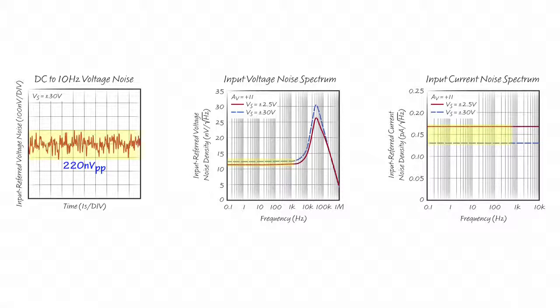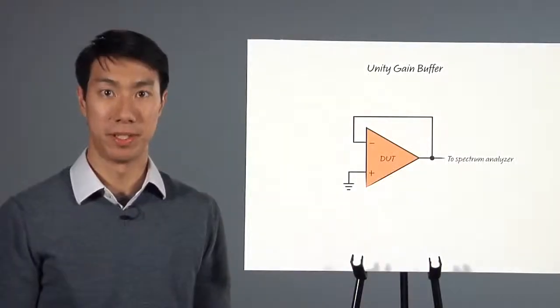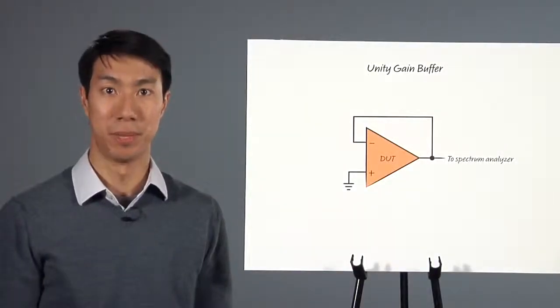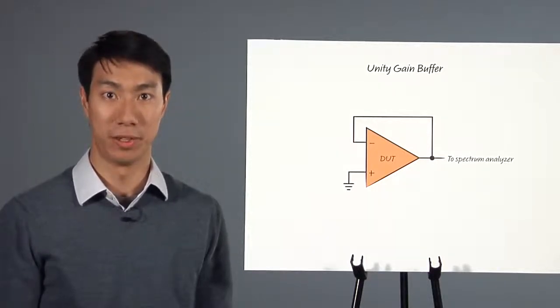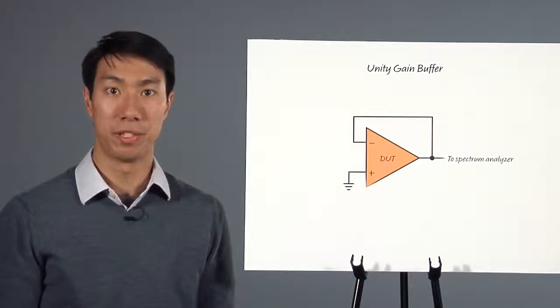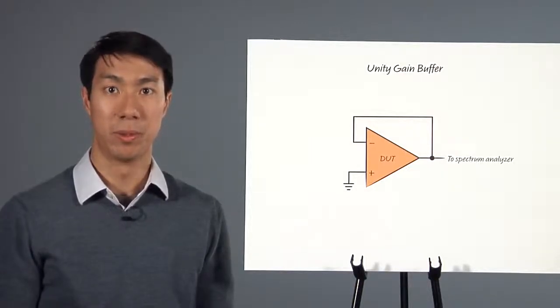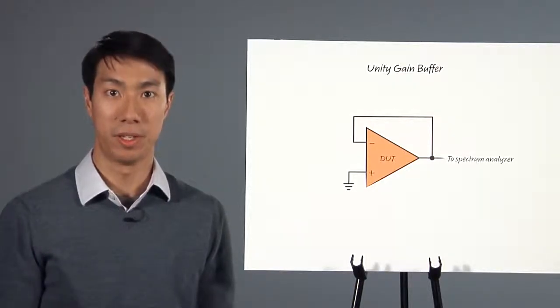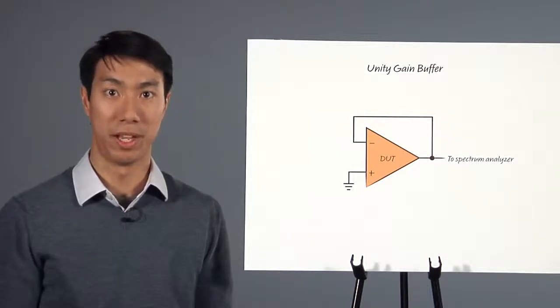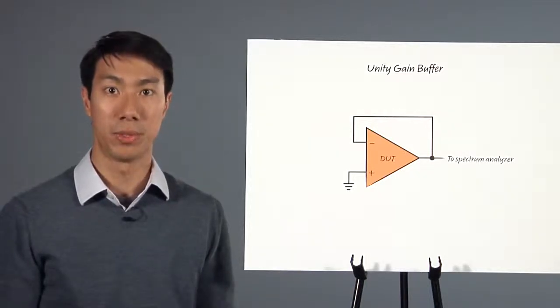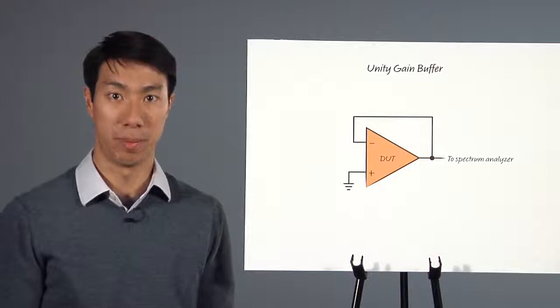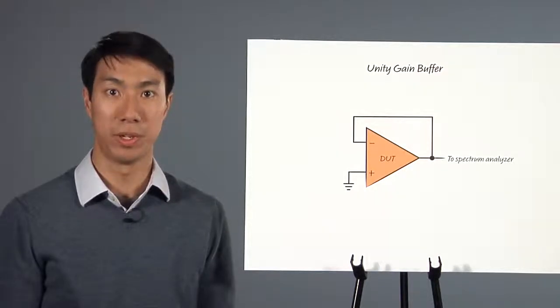For the most part, these devices behave pretty much like normal op-amps. But in some designs, the offset correction circuitry that makes great DC performance possible may generate disruptive signal artifacts. One of these artifacts is called voltage ripple, which is a series of idle tones at the op-amp's self-calibration frequency and its harmonics. These spurious signals are generated within the op-amp and will be present even when no input signal is applied.